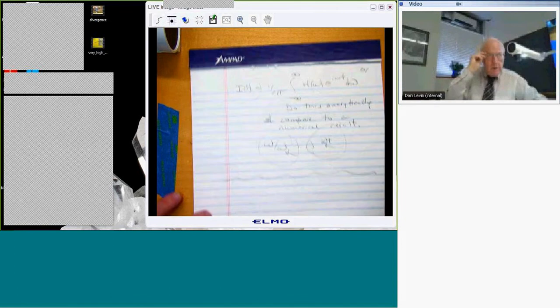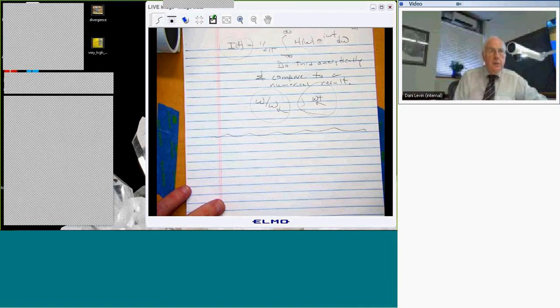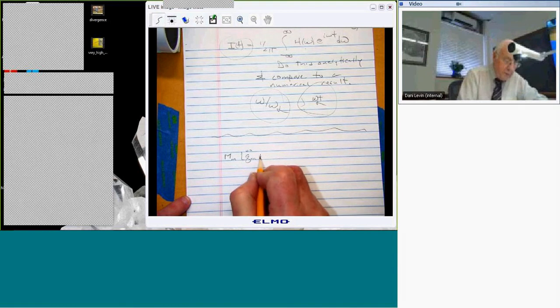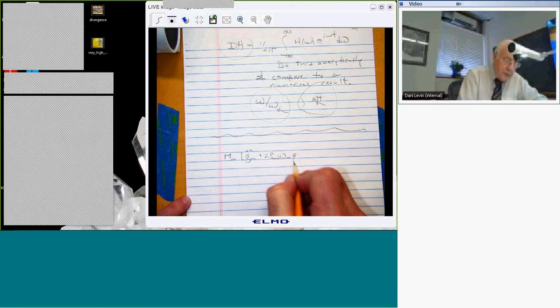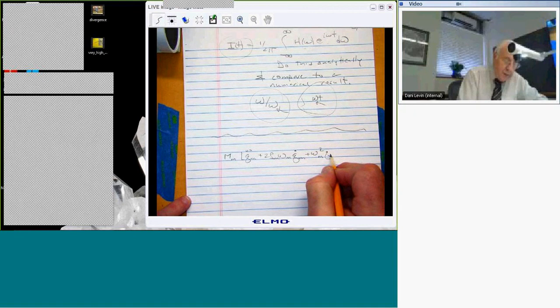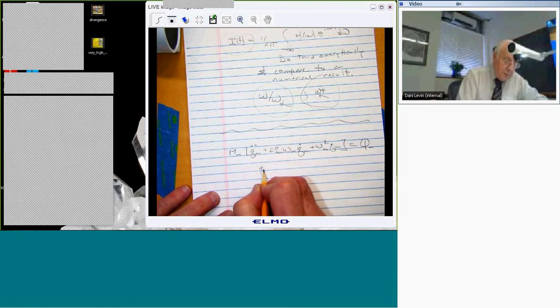The most general form, at least for aeroelasticity and for lots of other systems as well, of the equation of motion looks just like the equation we were describing. Let me write it down for you. It's M sub m times q sub m double dot. Does that look familiar? Plus 2 zeta sub m omega sub m q sub m dot plus omega m squared q sub m equals capital Q sub m, where q sub m, small and large, are both functions of time.